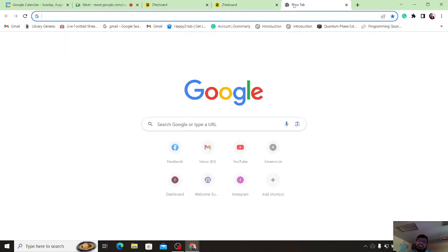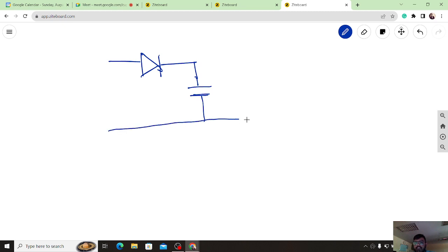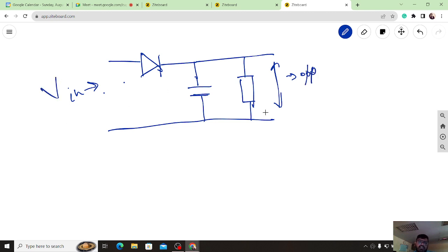So what we do in this sort of envelope detection is, let me draw the circuit for envelope detection. So basically a signal is coming here. Let me draw the detector circuit first. It takes a diode and then it is connected through the demodulation scheme, that is the detector, right? And another load is here, and the output is here. The input is coming here, and I'm getting the output voltage here. So this is V in and this is V out.